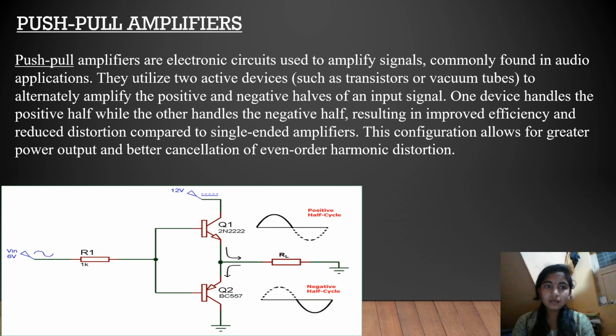Let us come to know what push-pull amplifiers are. Push-pull amplifiers are electronic circuits used to amplify signals, commonly found in audio applications. They utilize two active devices, such as transistors or vacuum tubes, to alternately amplify the positive and negative halves of an input signal.